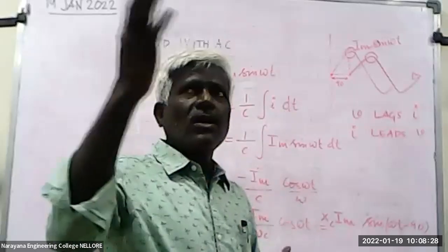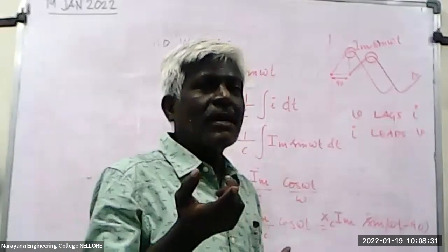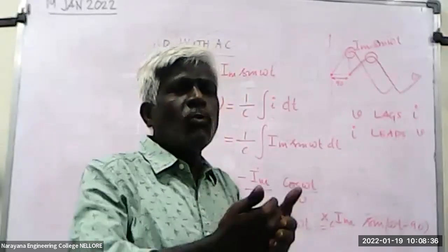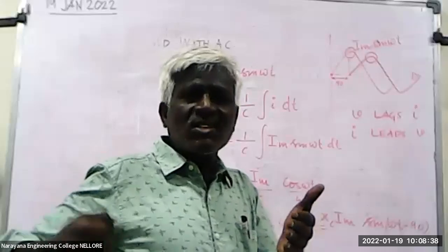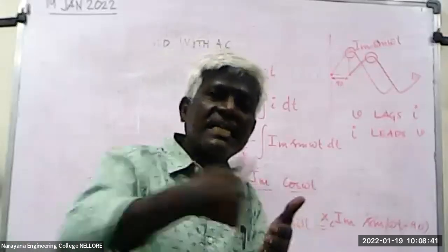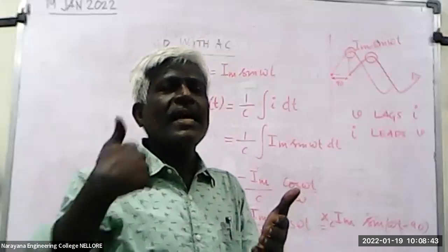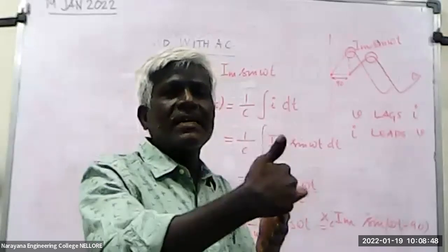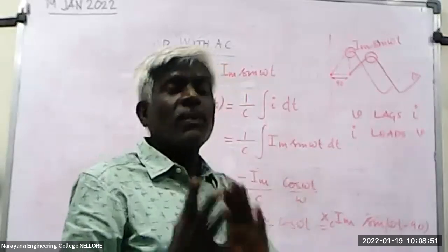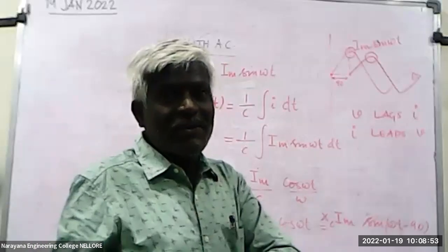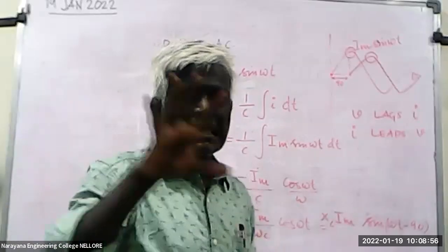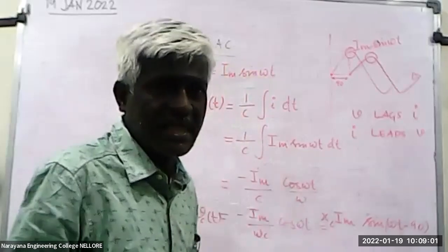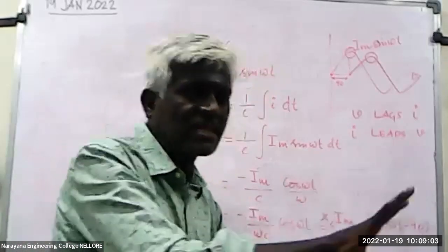Capacitance. So the loads are inductive loads, but intentionally, purposefully, we add capacitance so that, by the amount the current is lagging behind, the addition of the capacitance leads that current. Then voltage and current go together, so that the real power will be your apparent power. There is no reactive power, because it is getting compensated. That is what we call reactive power compensation by adding capacitor banks.